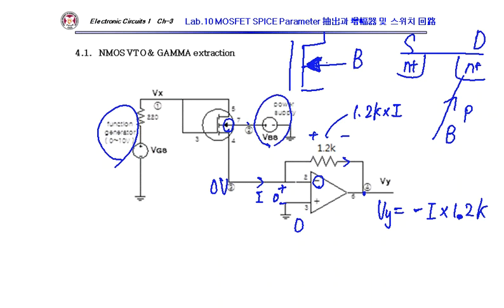I think this MOSFET you can bias. I'm not sure exactly, 3 volt, minus 3 volt. Those are DC biases for those MOSFETs. And this VBB can be 0 volt, the most negative potential of this MOSFET circuit. You change this V value and monitor the I current here. Then you can see, if you put square root ID in Excel,